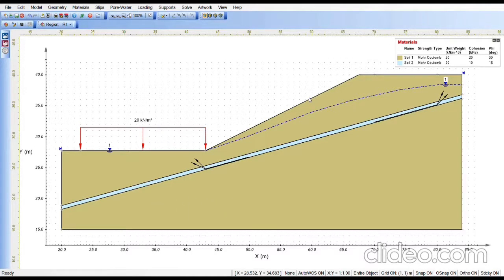For the trapezoid type, we enter just the same steps. We enter the acting points section and the point load, and then after that we can click OK. So in this example, we have two kinds of distributed load, the constant type and the trapezoid type. And after the distributed load has been shown, the next step is that we have to analyze the model.